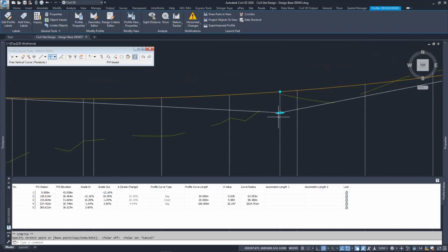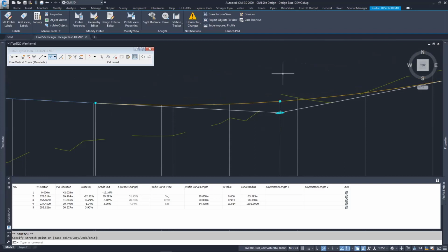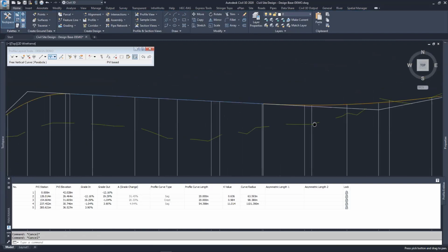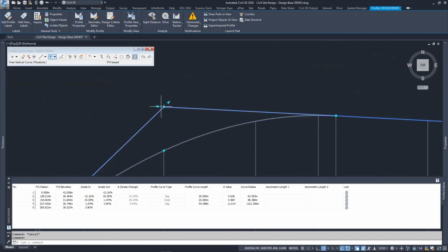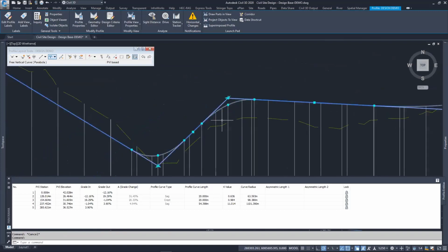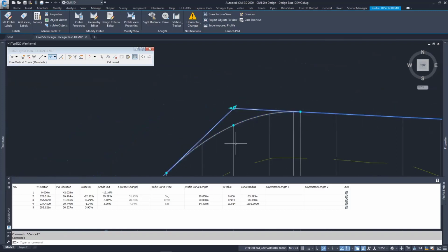It's free in CAD. And just on that, you also have these other grips where I can manually adjust the vertical curve length just by sliding that up and down, because it's free. The other one I'll show you is these triangle grips that point off in the direction of the tangents that are applying. So if I want to maintain that 0.5%, which has been changed now to 1%, I'm just going to make that -1.